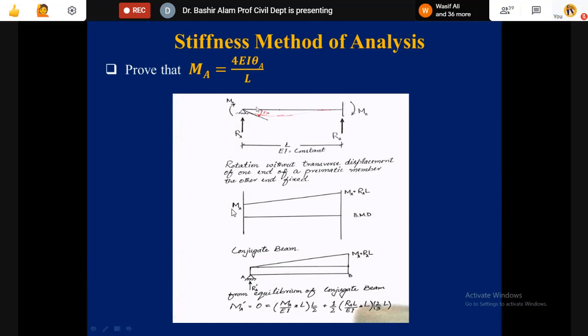This is a beam now. At A, we will be giving θ, so we have released this and converted this support to a hinge support. The far end is fixed now. A clockwise rotation is given, and let's assume, this is an assumption, MA is clockwise, MB we give clockwise, and the support reactions, as these supports can give the vertical reactions also, so RA and RB in the real structure. L and EI, you can have now these properties.